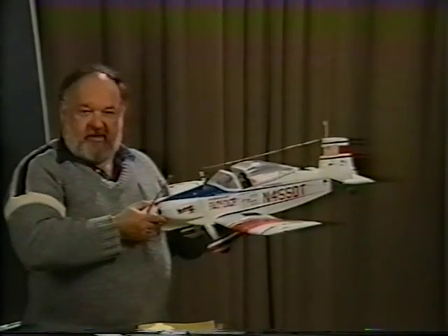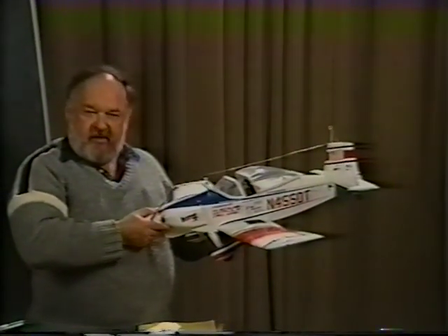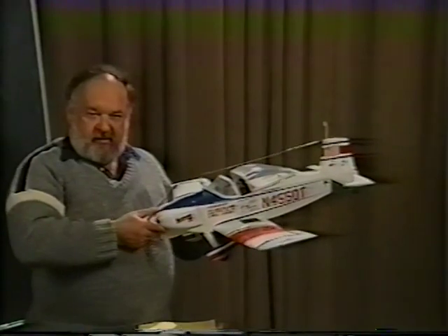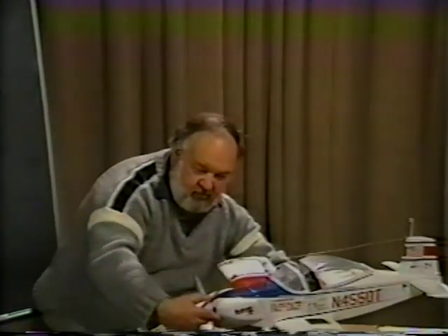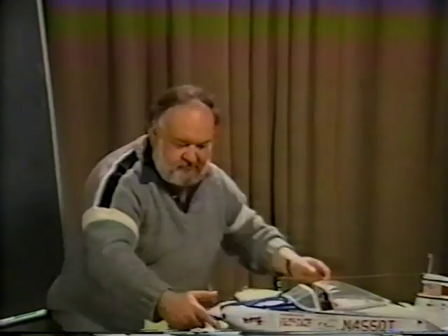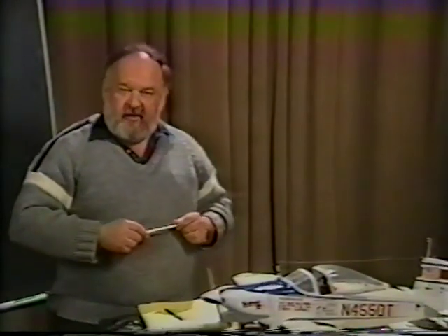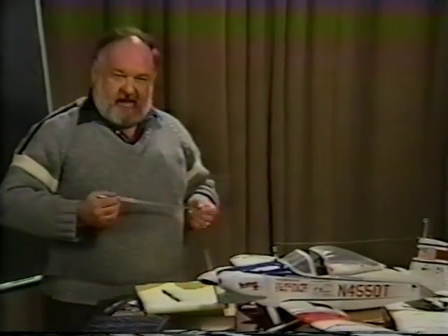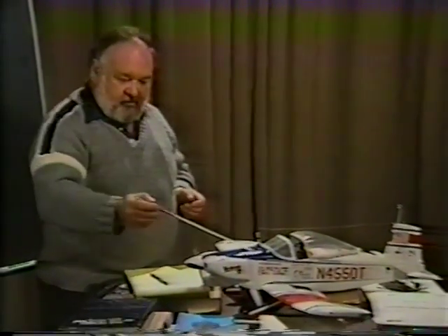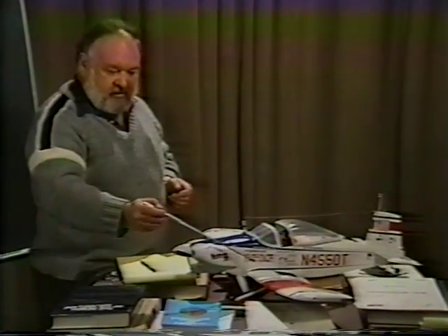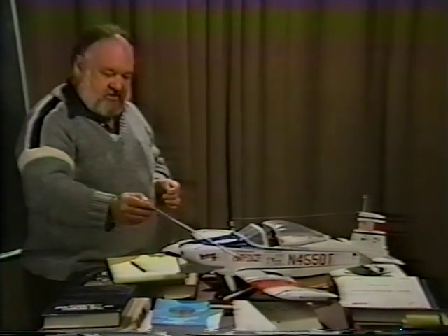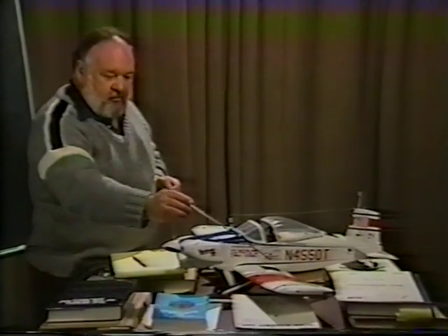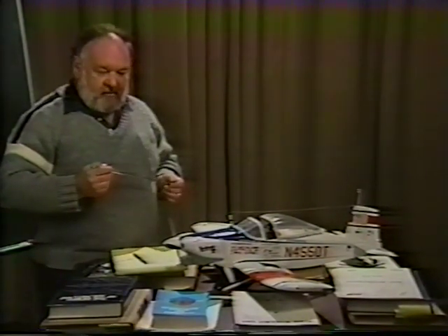And that's really a pretty clever approach he has, because a lot of times the designer will have the break on the inboard section of the wing close to the fuselage, in this region in here, but that also happens to be where the highest stress concentrations would be, because the loads are the highest on the spar right inboard like that. So in this case he probably saved some weight and made it a much simpler design by making it a one-piece spar with the breaks in the outboard portion.